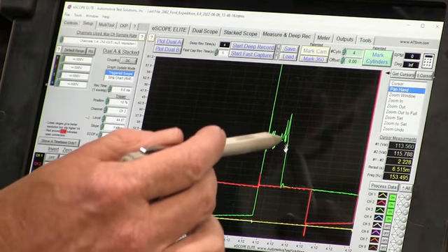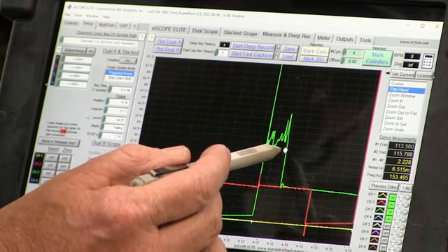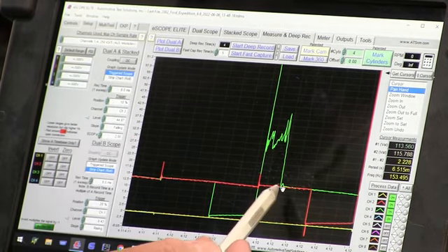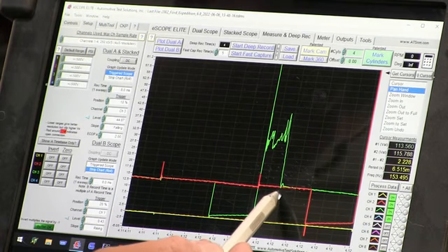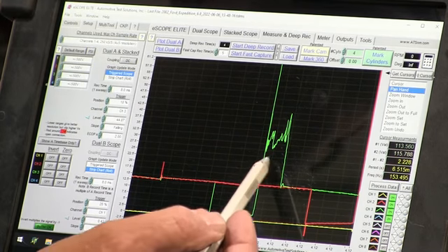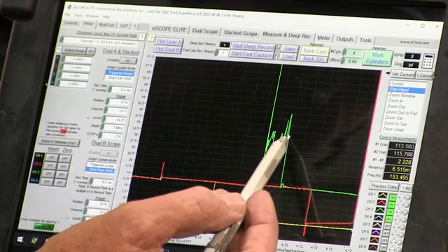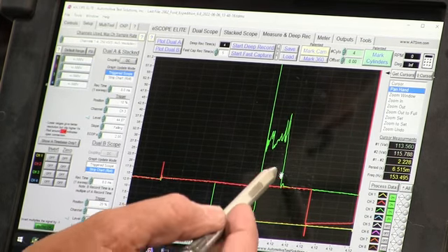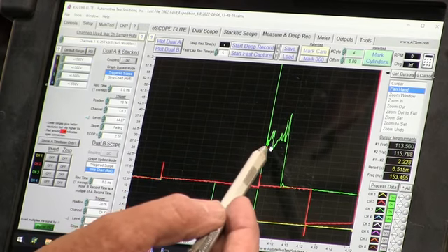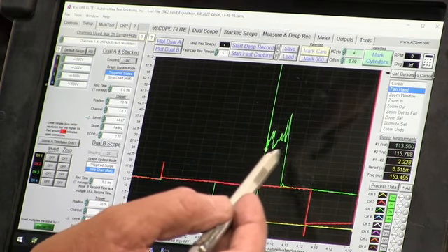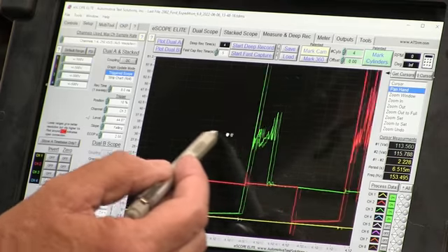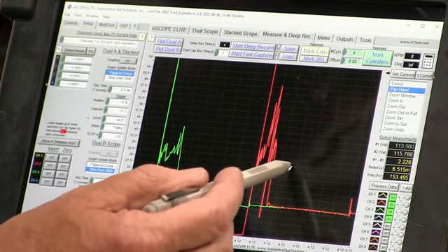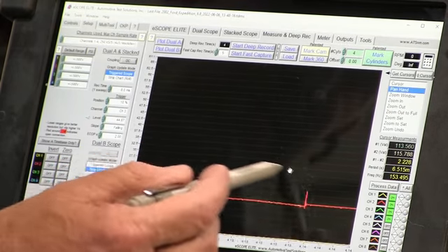Here, this one looks fine. We dumped most of the voltage or the current out. The reserve capacity of the coil was dumped because we have a very small downward going tail. That tells me that we're getting rid of the energy across the burn of the plug, which is what we're looking for. When the tail gets too big, it's telling me I have too much energy. It's having a hard time dissipating all the energy across the plug gap. Now that's pretty good. Again, this one's a little worse, but that was a pretty hard snap, guys.